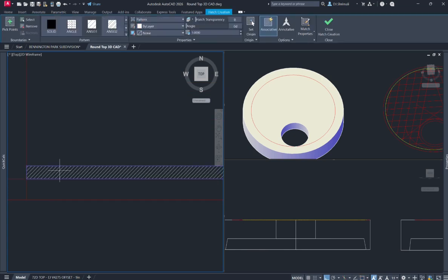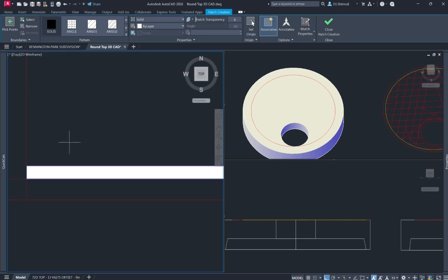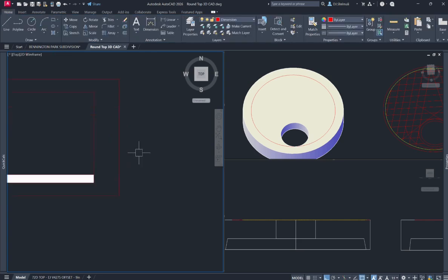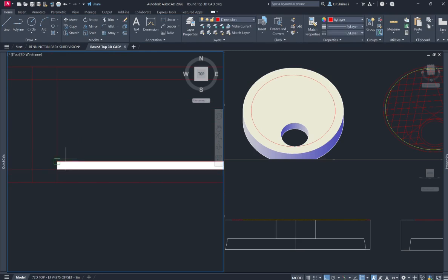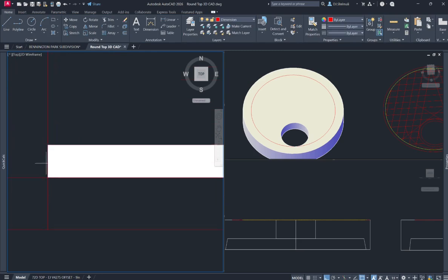Okay, so after that I'll create the circular rebars, the section in the other direction, since the bottom one is going to look straight, which is the resisting bar or main reinforcement, and on top of that we'll use the alternate reinforcement or the longitudinal reinforcement, or you can say the reinforcement in the other direction. Okay, for that I'll create a circle and put the hatch in it, so that it looks like a section of a rebar, and I create a block of it and then use the array command to create the reinforcement.